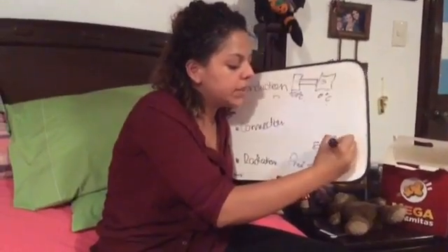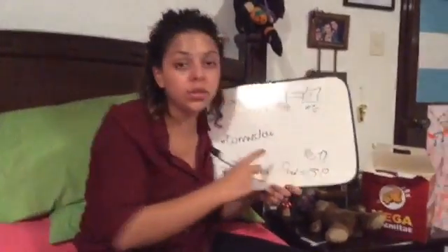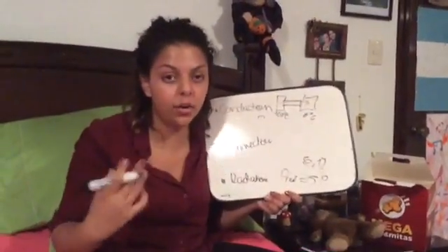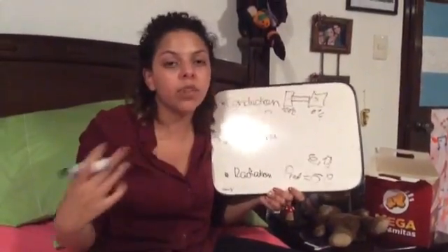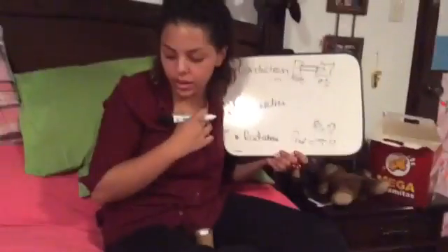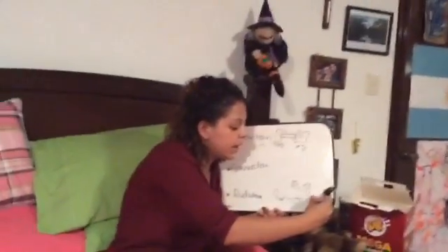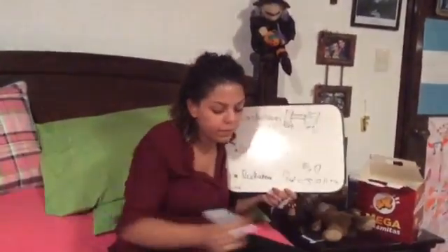Although there is no object in the universe that has exactly any of these values. 0 would be something that does not radiate at all, and 1 would be the perfect radiating object. So we normally have values between these, times the area, times the temperature to the fourth power. So these are the different ways we have of transferring heat, and all of them can help us solve different problems.